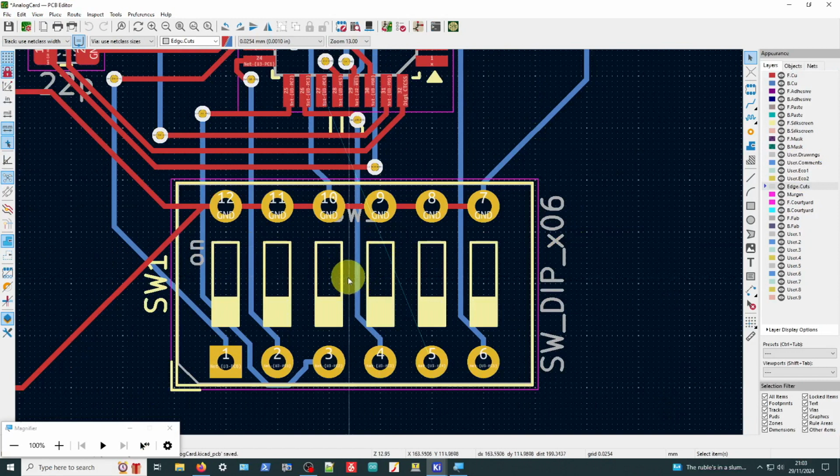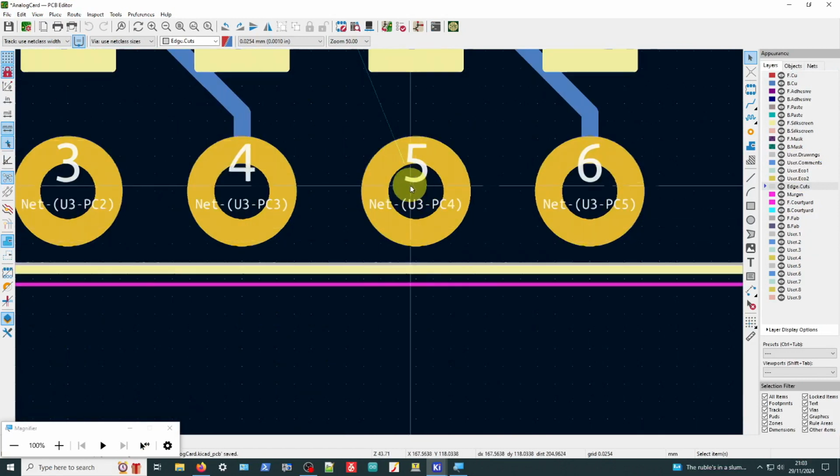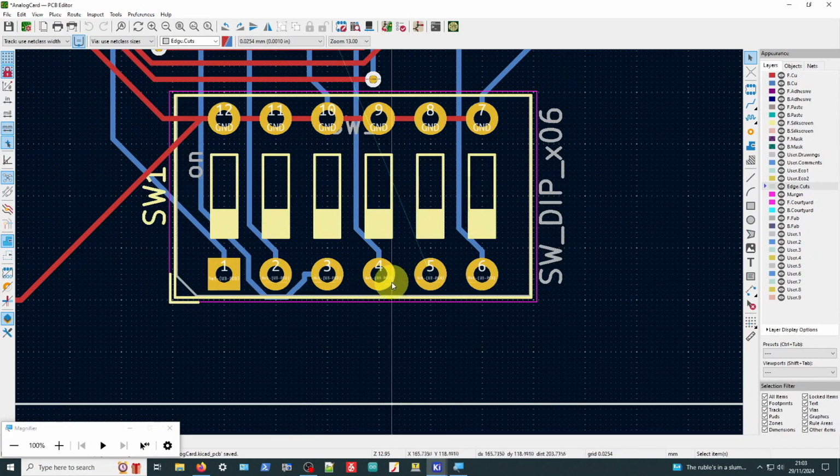Now, why isn't that connected? It's got to get to this dip switch here. All right, well, what's interesting is the dip switch is the wrong way around, because all of the grounds wanted to be down here just to get them out of the way, and it's routed everything through the switch, and it's left itself, because we're only using a 2-layer board.